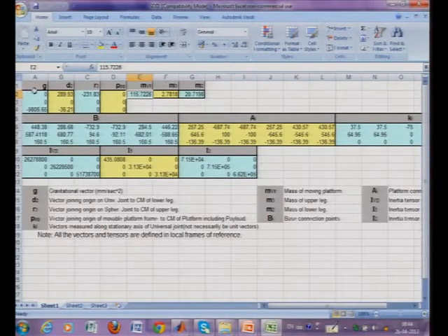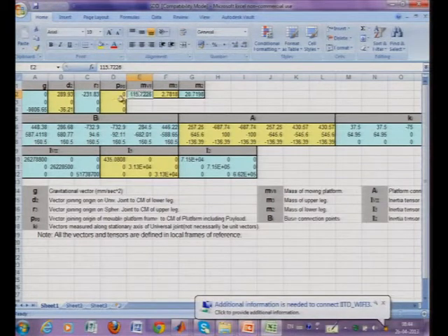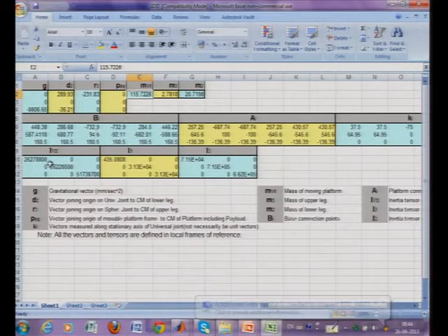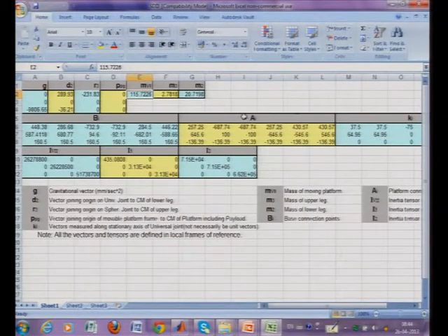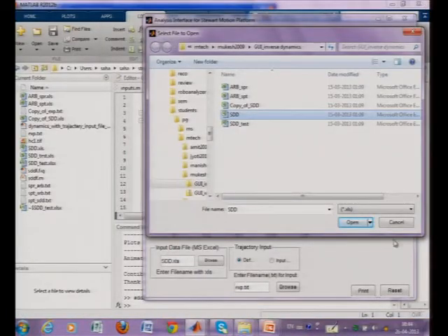So, it has all these parameters: g, the acceleration due to gravity, the d2, the origin to the mass center length, r3 from the mass center to the next origin, the masses of the 6th platform. So, this is related to the moving platform, and then we have all this geometric information here, and then inertial information here, and all this explanation is given here. So, for your Stewart platform you have to change this data, and then you go back to the slide.